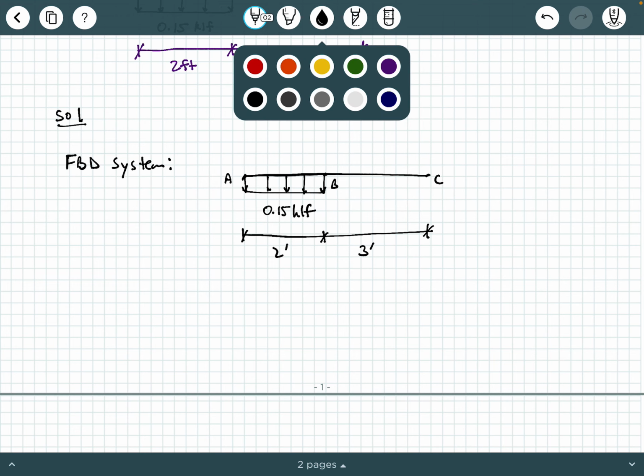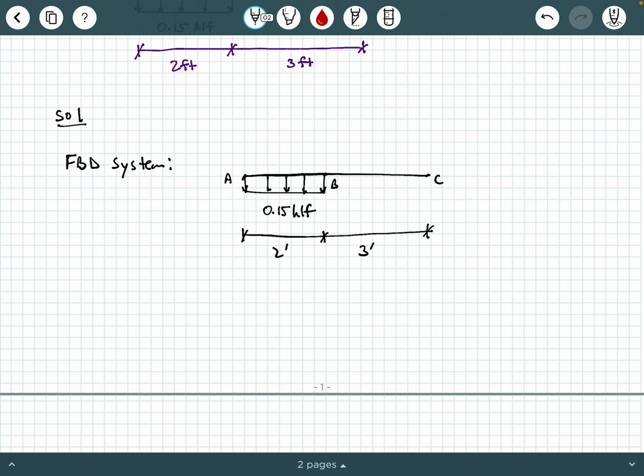Now, what is happening at these 3 points? Well, we have these 3 axially loaded pin-connected rods. So you're going to have a vertical force develop in each of these rods, FAD, FBE, and FCF. Now if we look at the free body diagram of this system, we have 3 unknowns. We have these 3 unknown forces. How many equilibrium equations can we apply to this system?